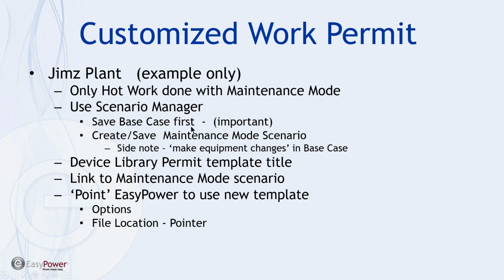If I need to change, and this is a question that's come up in the past, some basic element in my system, like a main or a motor or even a transformer, by making that modification in the base case, it will then be reflected across all the different scenarios, and I don't have to recreate the scenario. So a little word to the wise.